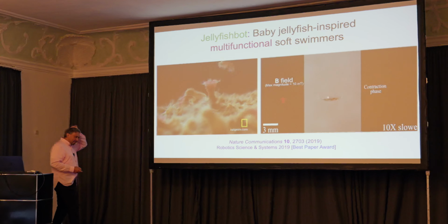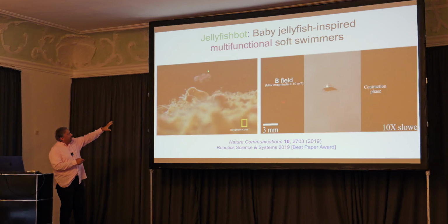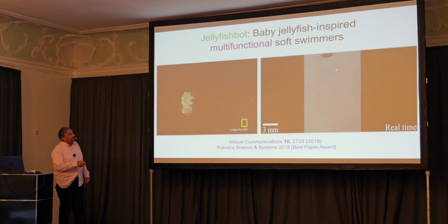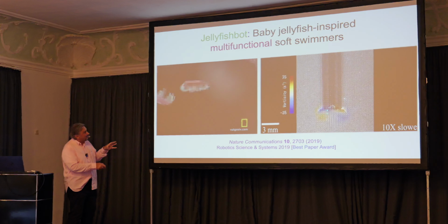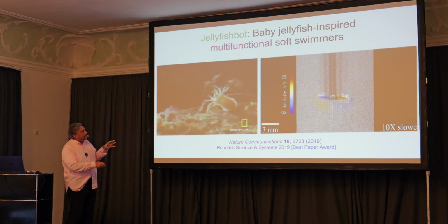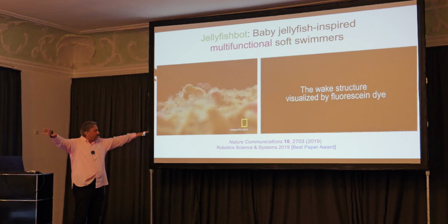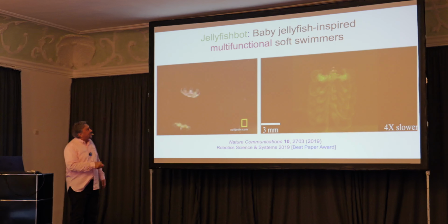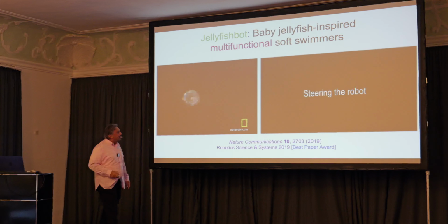But another fun organism, because I have done a lot of bioinspiration for robotics, we have been very intrigued by these small jellyfish. And for the first time, we could create a robotic jellyfish at the same size, same morphology. This is fluid dynamics. You can see experimentally how the fluid is deforming, because it's going down fast with a large area, going backward with a small area and slower. So this is high Reynolds number. This is not small Reynolds number. This is the wake of the fluid.